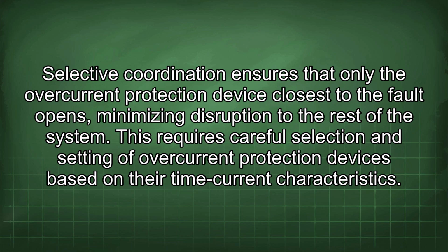Selective coordination ensures that only the overcurrent protection device closest to the fault opens, minimizing disruption to the rest of the system. This requires careful selection and setting of overcurrent protection devices based on their time current characteristics.